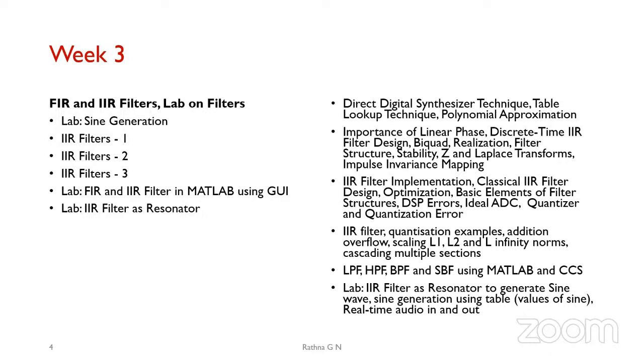This is the second error that we have to take care of. And then the third error is a math error. Basically, we'll be doing multiply and accumulate in the hardware. So I know that my number system does not let me extend beyond 16 bits in these DSP processors we are considering.